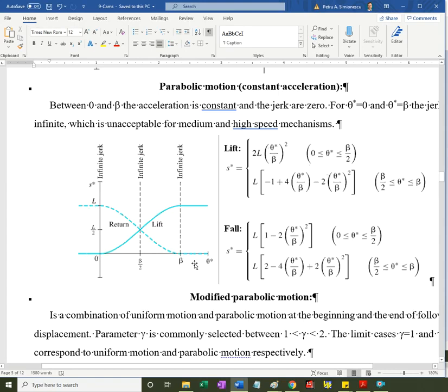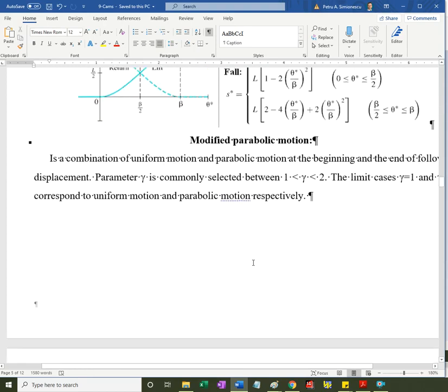and then your other concerns. Pressure angle is one of them. Size of the cam, material selection, you know the drill. And again, the way you blend in the lower dwell, upper dwell, it's based on the follower motion that you select. And I said this is still not the best one for fast rotating cams.